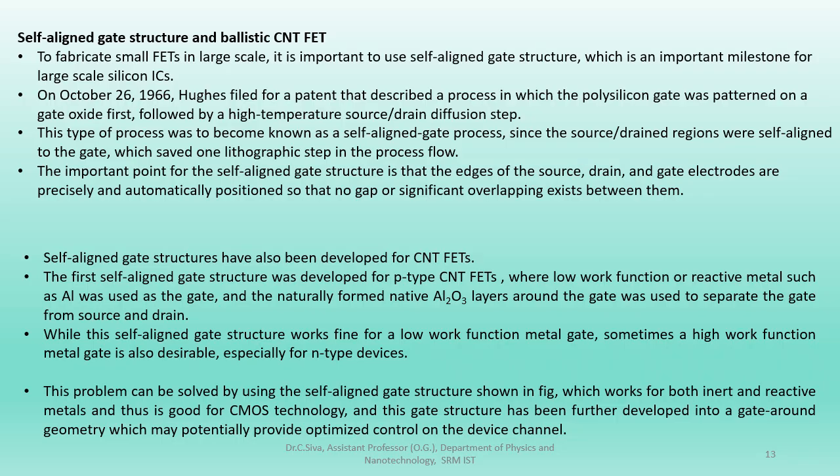Self-alignment structures ensure precise positioning of gate, source, and drain, which enables short channel length without overlap. Advanced designs now include gate-all-around geometry, giving even better electrostatic control, which is essential for CMOS logic at nanoscale dimensions.